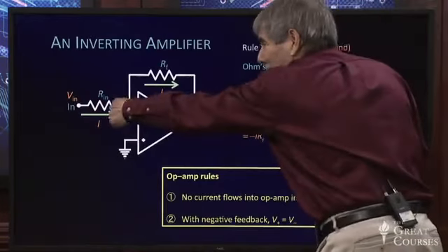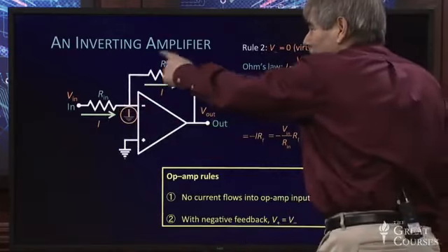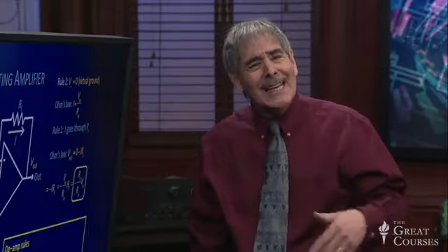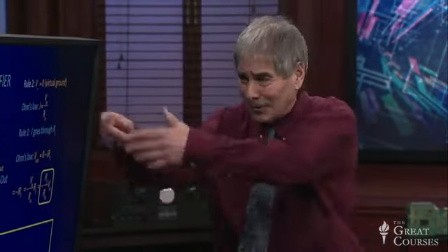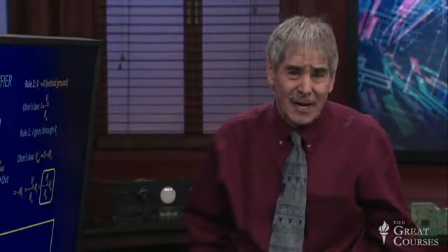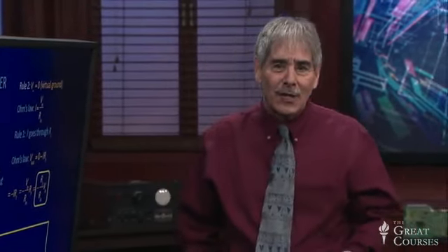And if you needed to make this input resistance 100 kilo ohms and you wanted a gain of 10, the feedback resistor would need to be 1,000,000 ohms, and that's beginning to get a little too big for this op-amp, comparable to the intrinsic resistances inside it. So you can't really use the inverting amplifier configuration to make an amplifier that has a very large input resistance. Now, in many cases, that's not a problem, but it could be.